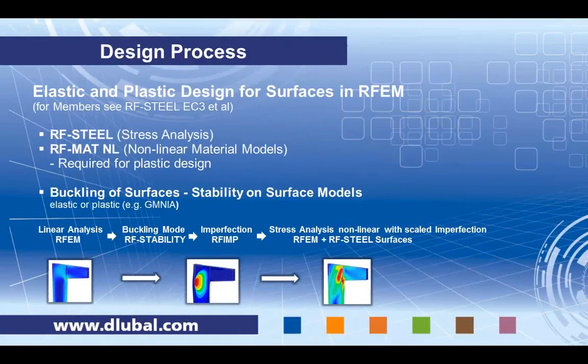When designing elastic and plastic models for surfaces in RFEM, we need additional modules. The main modules that we need are RF-STEEL, which is a stress analysis, which compares existing stresses to a fixed allowable stress. We also need RF-MAT NL, which gives us nonlinear material model capabilities, and this is required for plastic design.